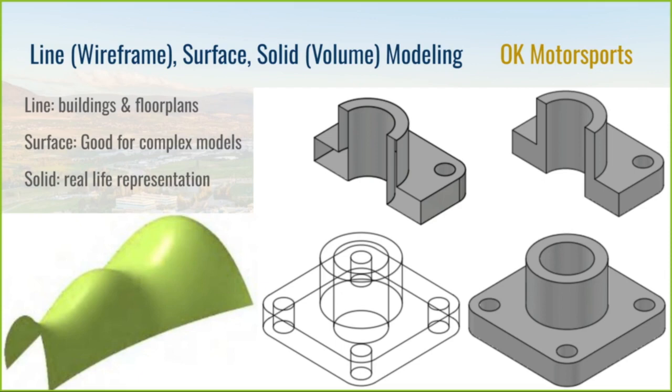It also gives you information about how deep things are and where they are, and it's nice if you have a lot of components that are all built together and things are meshing weirdly, or there's a lot of complex stuff going on. You can turn the wireframe on and say, okay, I know that this face does touch some internal thing that I can't zoom into because it's hidden. So wireframes are good for that.